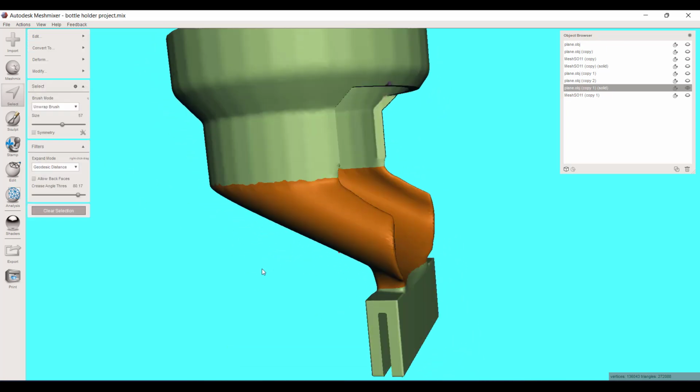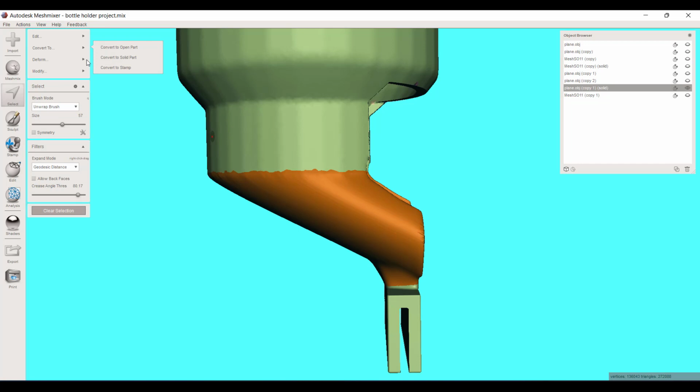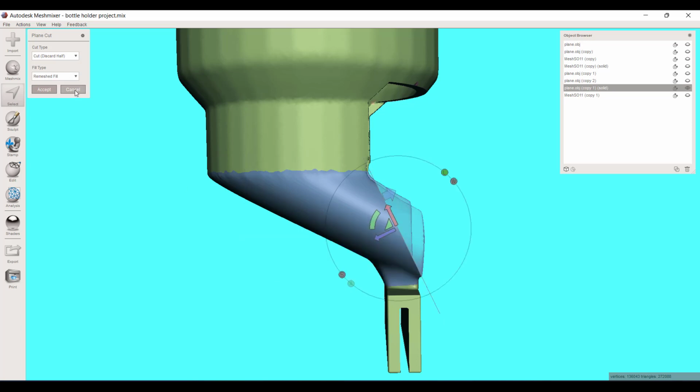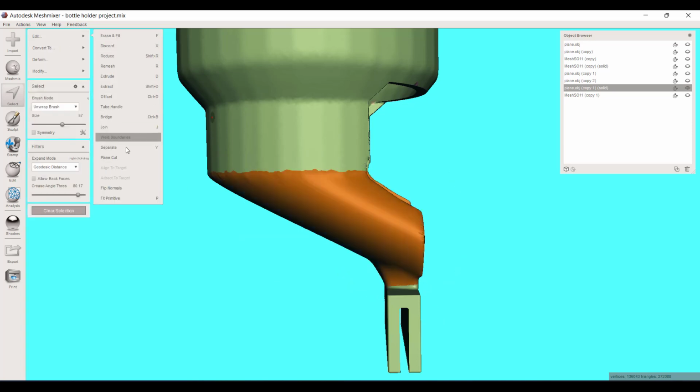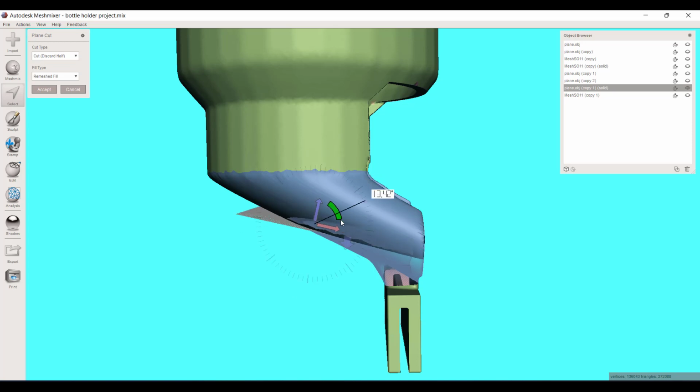While I got this selected, I'm thinking now, let's minimize how much resin we use. So under Edit, again, if I use plane cut under Edit when I've got a selection, I could just plane cut this blue portion. And actually, let me cancel that. I keep doing this manually when I should be doing it with this thing so that I keep my plane cut symmetric.